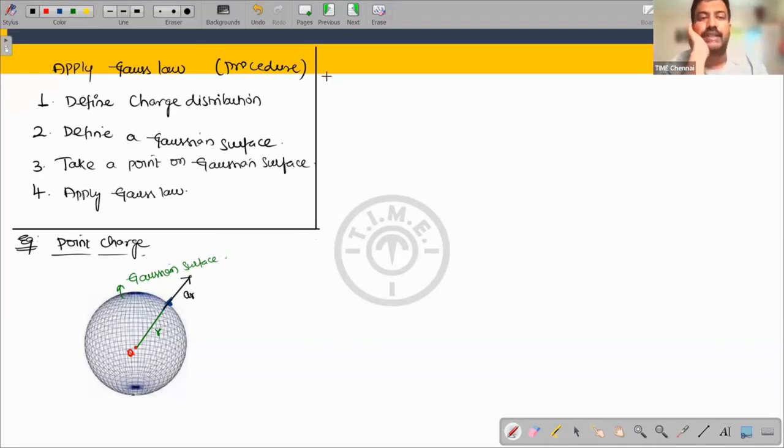So the electric flux density that is going out, because I took a sphere, spherical coordinate system, will be D_r a_r. You know the general form is D equals D_r a_r plus D_theta a_theta plus D_phi a_phi. But now D is moving radially outward, no D_theta a_theta, no D_phi a_phi. D must be D_r a_r. That's the first thing.